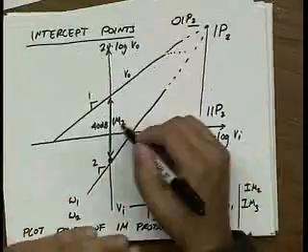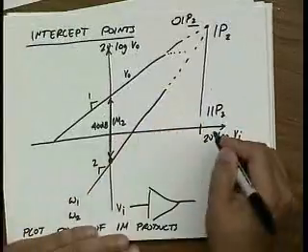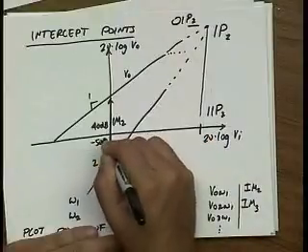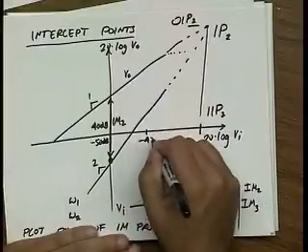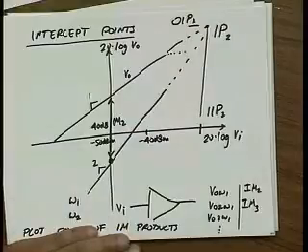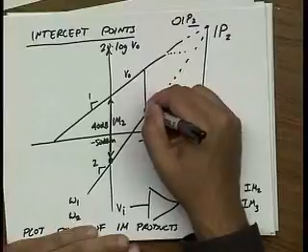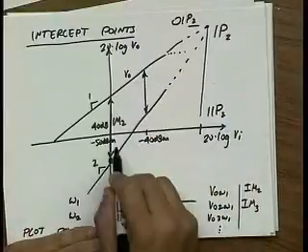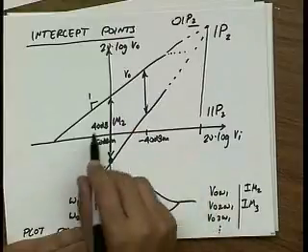What's interesting is that as I change my input power, let's say this, for instance, corresponds to minus 50 dBm input power. Let's say I go to minus 40 dBm. Well, that means that my IM2 changes by also 10 dB. So if I change the input power by 10 dB, the IM2 will also change by 10 dB.